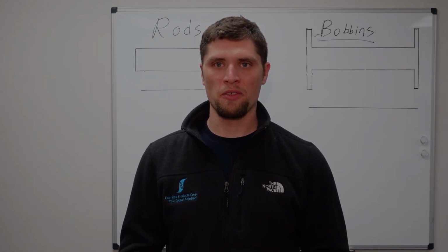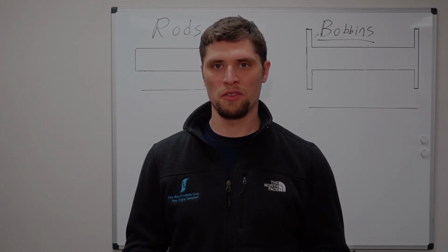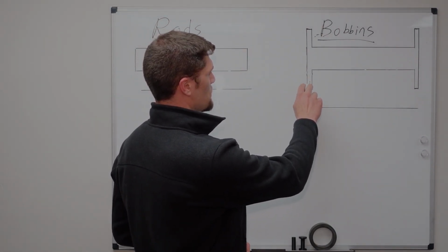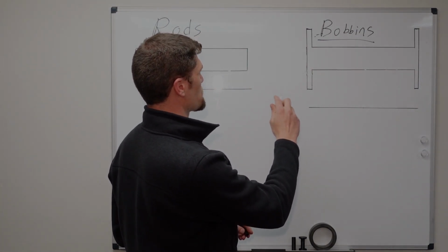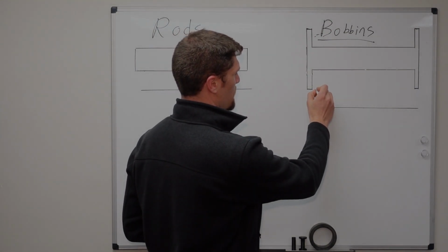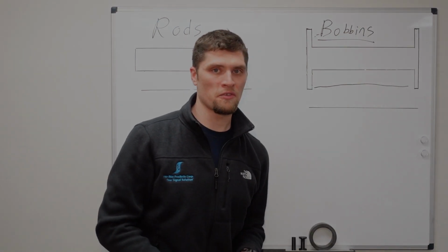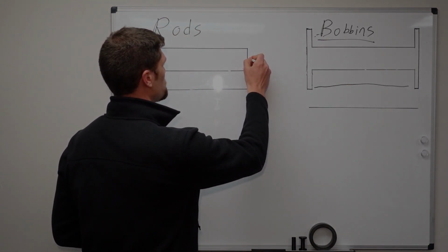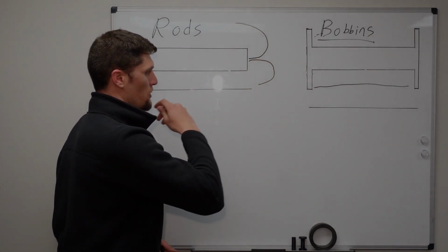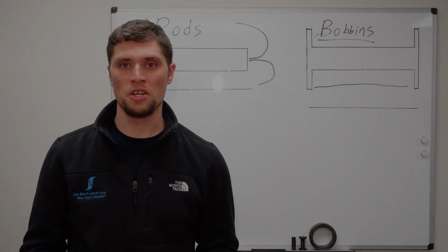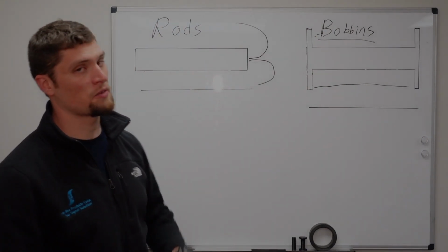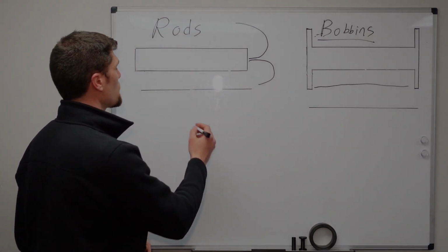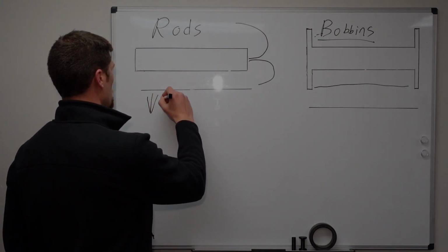The more of the magnetic path that is going through air, the more dampened the properties of the ferrite core are going to be. So right off the bat, a bobbin, generally being a similar size and diameter as a rod, is going to see less of that magnetic path length be through air, since a lot of the flux is being channeled through those flanges and across one another. What we saw on the rod was the flux propagating out from the ends of the rod and around, meaning that as a percentage, less of the flux is contained within the confines of the core. So what does that mean? The most obvious one right off the bat is that rods generally are going to have a lower AL.